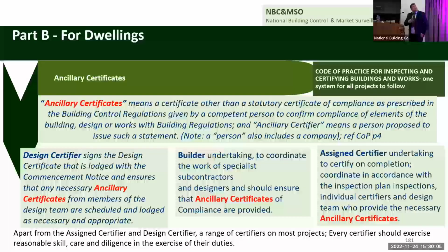So the design certifier signs a design certificate that is lodged with the commencement notice and ensures that any necessary ancillary certificates from members of the design team are scheduled and logged as appropriate. The design certifier here mightn't have done the fire cert application, but he might want an ancillary design cert for that. He mightn't have done the DAC, and he might want an ancillary design cert for that as well.